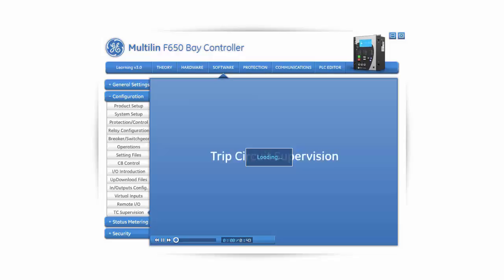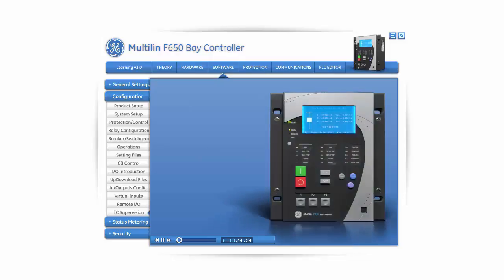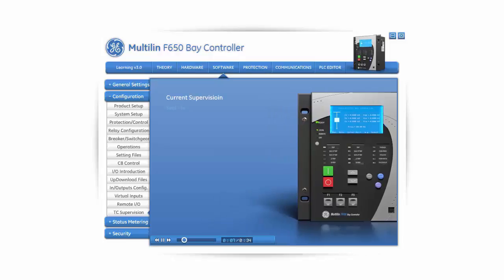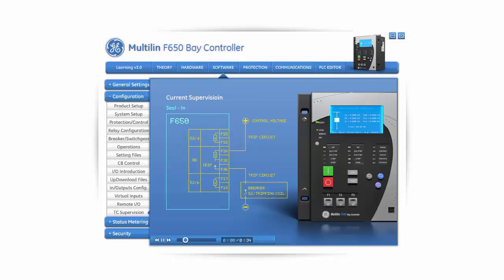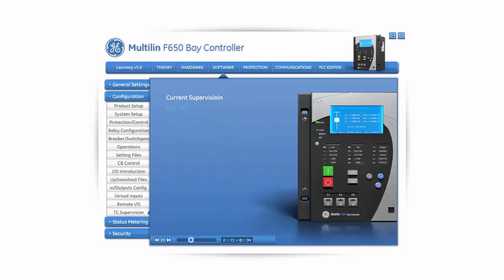As discussed in the hardware section of this CD, trip circuit supervision circuits are auxiliary circuits that monitor the tripping circuit to ensure its proper operation. This is accomplished via two main trip circuit supervision features. The first is to use current supervision in the tripping circuit, which is designed to protect the relay tripping contact output by sealing it closed in the event that the breaker fails to open. This prevents the trip contact output from breaking open operation currents, which it is not intended to handle.